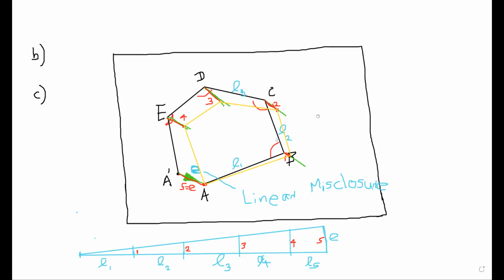This yellow color polygon is called the corrected polygon. The corrected polygon is taken as this yellow one. Now you can see the shift is very small for B. For C, it would be a little bit more, as we are taking the cumulative one, right? So this is the construction to get the corrected polygon by using the graphical method.